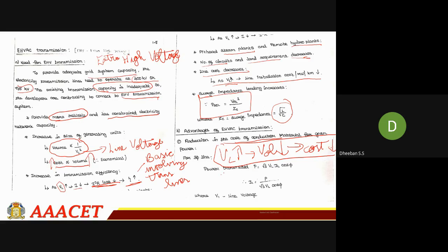So that's what they have given here. So the power loss, they will be connecting with it. First, they will be taking the power to be transmitted P. So it is nothing but root 3 VL IL cos phi. So your IL will be equal to P by root 3 VL cos phi. Okay. So next is the power loss. We'll be defining all the things.